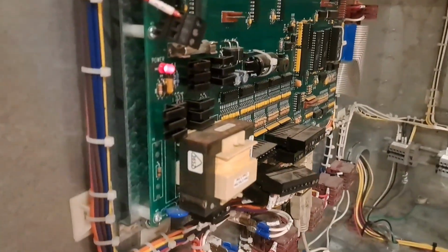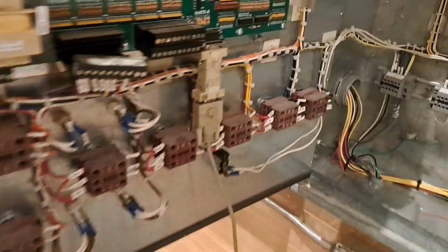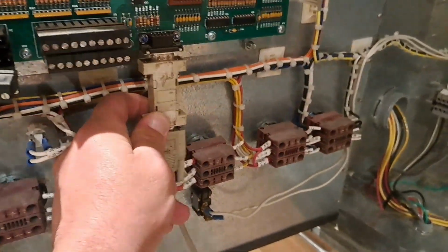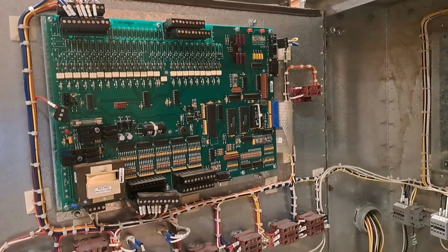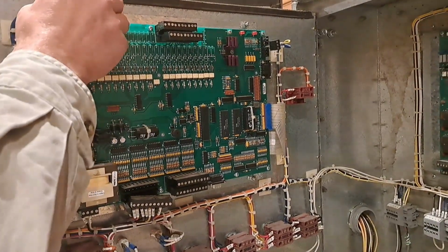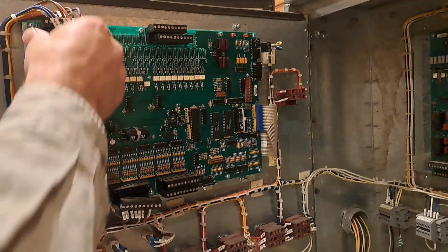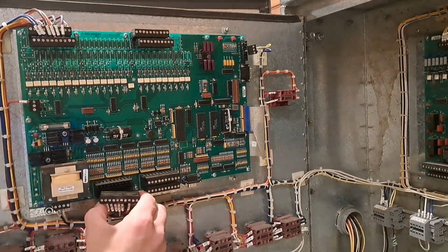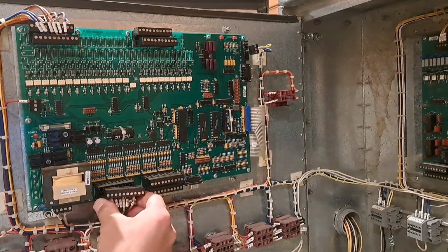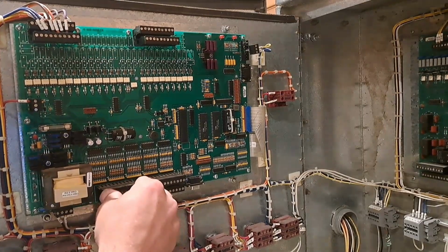So we go over here, we turn the power off, we unplug our programming cable, we plug in our wires that we previously unplugged. We make sure we line up the pins. That way they are plugged in correctly and everything works correctly without frying anything.